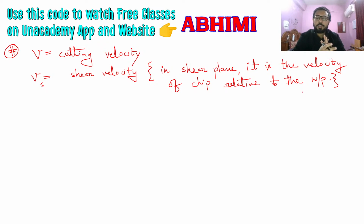So this shear velocity is in the shear plane, and it is the chip velocity relative to the workpiece. So that is your shear velocity. And then we will have chip velocity, which is the velocity of chip over the tool face, the rake face. So that will be chip velocity.